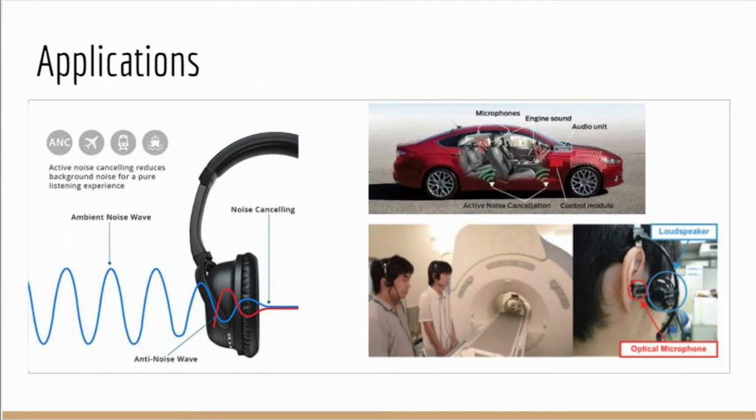There are numerous applications in active noise control which have been shown to be most successful in situations where low frequency noise is the dominant problem. So we first have active noise control headsets, which can reduce an additional 10 to 15 decibels compared to the usual headsets for up to 500 hertz. Then there are the feed-forward headsets designed specifically for noise reduction in nuclear MRI that require headsets without metal. Finally, we have active noise control for car engine firing sounds, especially at higher speed, and especially for modern cars, which tend to be lighter and have smaller and more powerful engines.